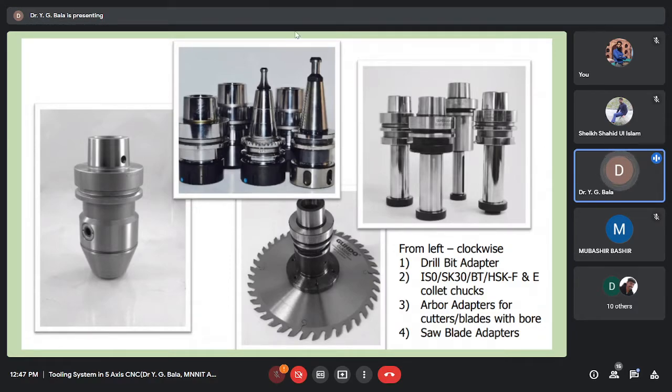Generally, this will come with the pull stud. On top of one picture, you can see a pull stud. Based on the roller mechanisms, either a ball mechanism or a collet mechanism, we can insert this part in the spindle head. For engaging and disengaging, the entire part will not be damaged even after a long time. Only the pull stud will wear.